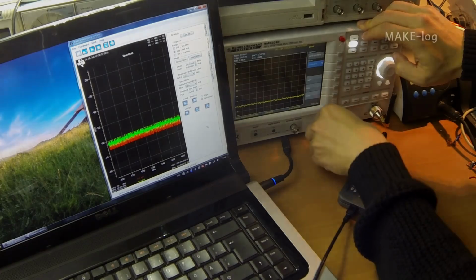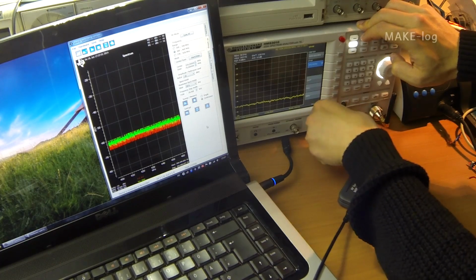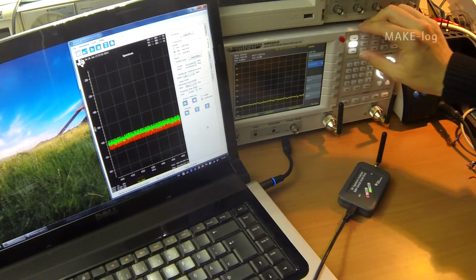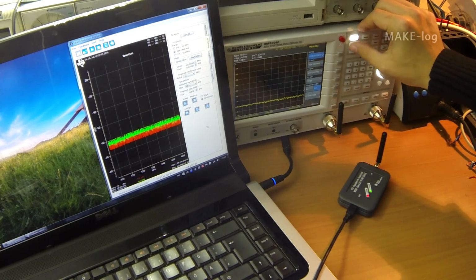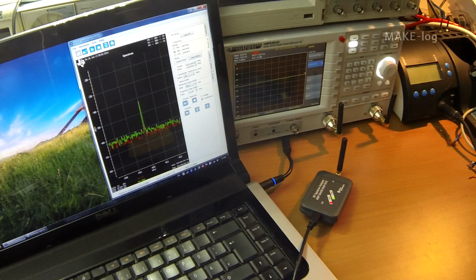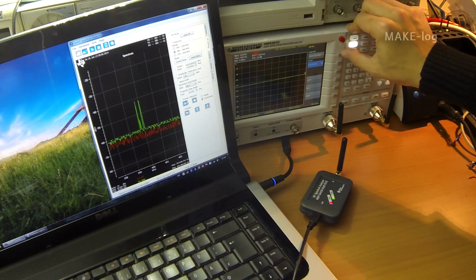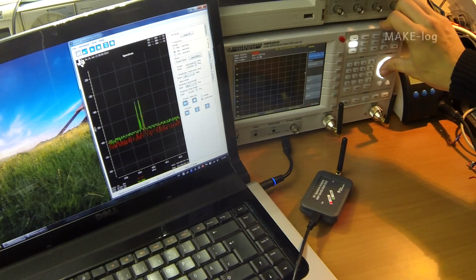I would like to test the Texas Instruments spectrum analyzer for other frequencies. For this I put an antenna to the tracking generator of the HAMEG spectrum analyzer and set it to different frequencies. The TI spectrum analyzer program shows us two curves. One is green, it shows us the maximum over time, so the maximum value that has ever occurred. The red curve shows the actual value.